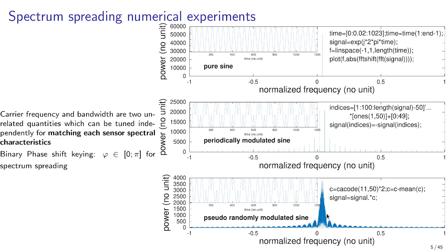In terms of spectrum, the spectrum has been spread as a continuous spectrum by this pseudo-random pattern of phase flipping, and this is closely related to Shannon's information theorem, where the spectrum bandwidth relates to the amount of information that can be transferred. Here we see that the spectrum has been spread by introducing this timing capability, and only by using this pseudo-random sequence of phase can we detect the time of flight.